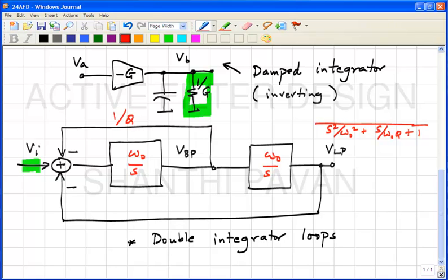This also gives us intuition about why things start to become unstable when transconductors have internal poles. Yesterday we saw that if every transconductor is associated with an internal pole at omega p, then if the omega p becomes too low, what do you think happens to the Q? Q will be enhanced, and if omega p becomes too small, then we saw that the non-ideal filter, due to this parasitic pole, can have poles on the j omega axis, which is equivalent to saying it's becoming unstable, right?